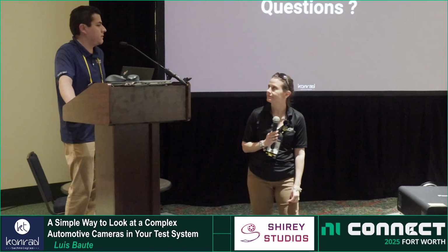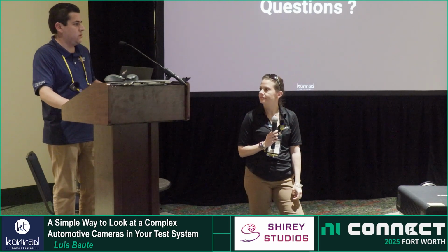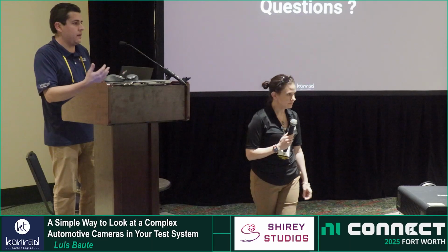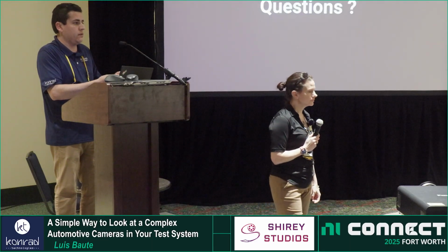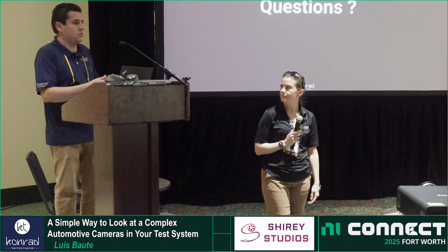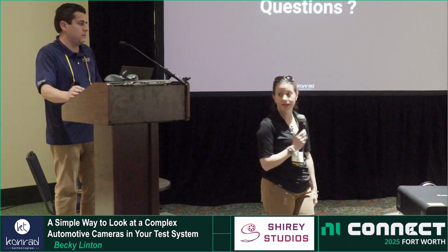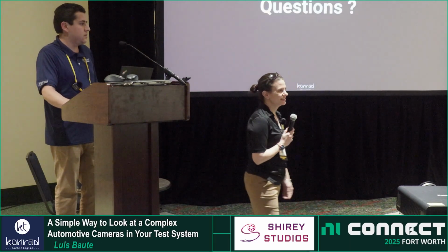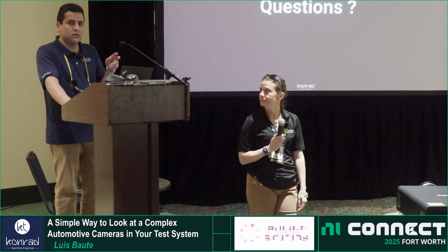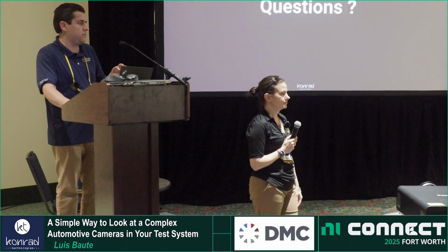For example, for one of the cameras, it was Sony, I think, we asked about how to generate a color pattern, a black frame, a white frame. They agreed and sent us the configuration, and we started using that to validate. This test was supposed to run for days and days and it was very hard to debug. We needed to fake a fault to make sure we were detecting it. So we decided to inject one, and when we configured these registers, we generated the black frame and were able to test our FPGA.